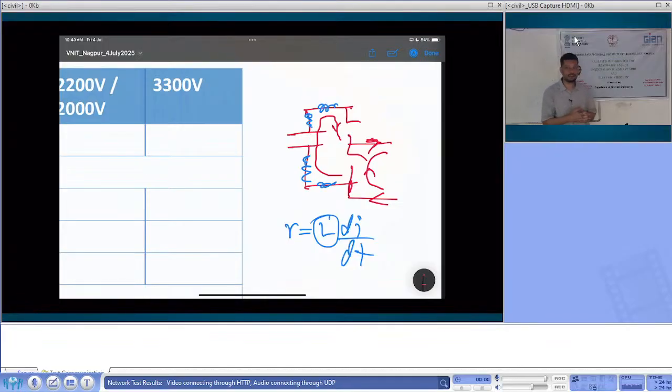But now, if you see, most of the initial designs are better with discrete. If you see the Tesla original motor controller, it's with discrete, right? If you open the majority of the motor controllers even now, they are with discrete. So there is some cost dynamics. Modules are effectively cheaper than making discretes, and all those things are there. But as a designer, discrete gives me much more flexibility. I can try out a lot of things there, right? Correct. That naturally cancels the EMI. Correct, precisely. You can place the devices top and bottom, minimize the inductance loop and so on.